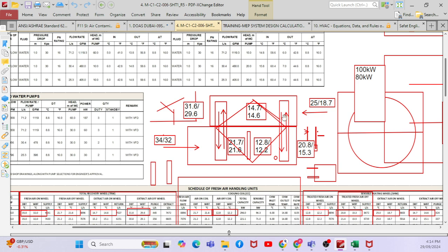If you go to the software from the manufacturer, and you enter this value, and you enter the airflow rate, it will clearly give you the off-wheel condition, off-coil condition, or off-coil, off-sensible-wheel load. What is the load? It will give you the conditions here. Exactly.